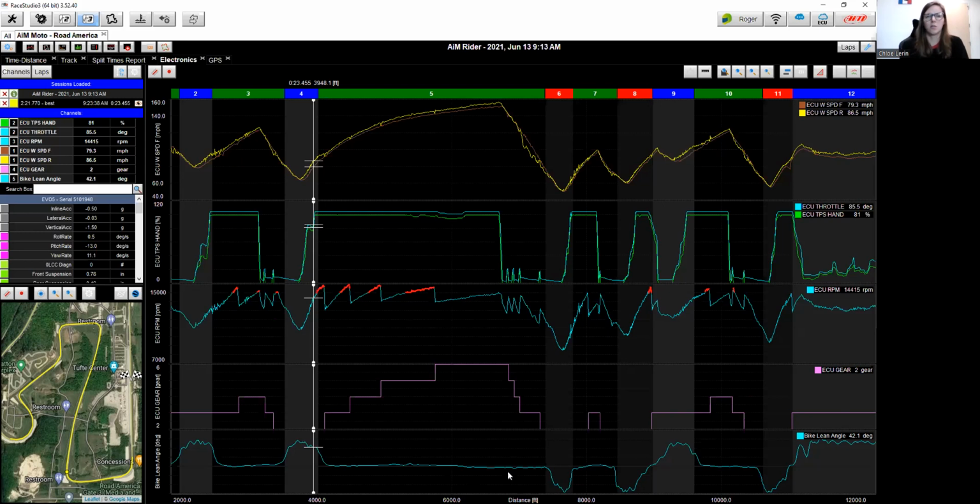You can somewhat reverse engineer or understand how the bike strategy or the ECU strategy is intervening. For example, by seeing, and those might not be perfectly aligned, but you can see that even though you're completely opening the throttle really fast, the way your throttle plate is intervening might be a little bit smoother. Yeah, so these are throttle progressivity. There could be riding modes. So if you're in engine map 1, 2, 3, you know, that could be what it is.